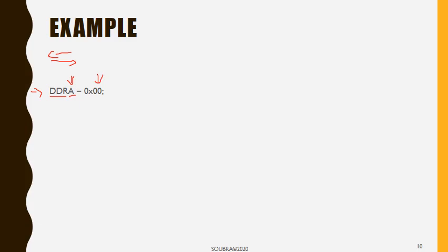All zeros means it's the default value, but using zeros, this means that the whole port is used as in. If I want it to be an out, well, I need to change the value zeros into 1. So this is a hexadecimal notation here, and this is equivalent to 0, 0, 0, 0. How many bits do we have in total? Correct, 8 bits for 8 physical pins.